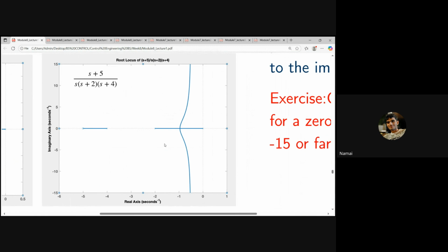And sir, by the way, the place where this intersects the x-axis is the centroid, right? Which is sum of poles minus sum of zeros over number of poles minus number of zeros. Yeah, okay. Why are you calculating all that? The computer will plot everything, no? Why do you need the centroid? I can get questions regarding this, because there were practice questions asking us to draw these plots.